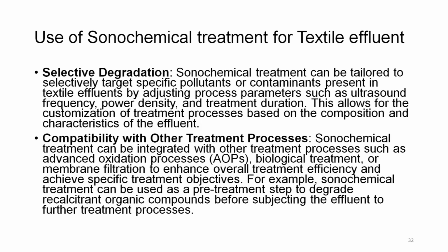Selective degradation. Sonochemical treatment for textile effluent can have selective degradation. It can be tailored to selectively target specific pollutants or contaminants present in the textile effluent by adjusting the process parameters such as ultrasound frequency, power density and treatment duration.